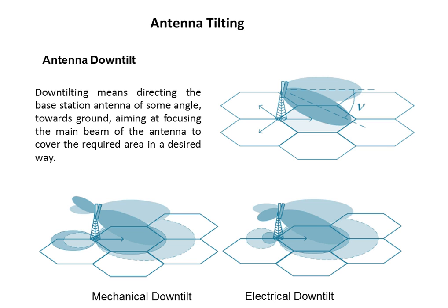Whereas in case of the electrical down tilt, since you are playing with the dipole area within the antenna, you are down tilting both the beams, the front lobe as well as the back lobe. Which is better? There are no specific studies; that all depends on what type of clutter and what type of radiation requirements you have within your cell design.